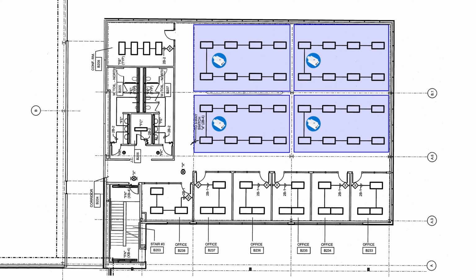Any fixtures that are 0 to 10 volt dimmable should also be connected to the advanced load controller's 0 to 10 volt output. Please keep in mind, your design will not define how you need to change the circuit, only that the blue zones will represent the fixtures controlled with the switched power from the advanced load controller or smart driver. It is up to you to define these circuits.